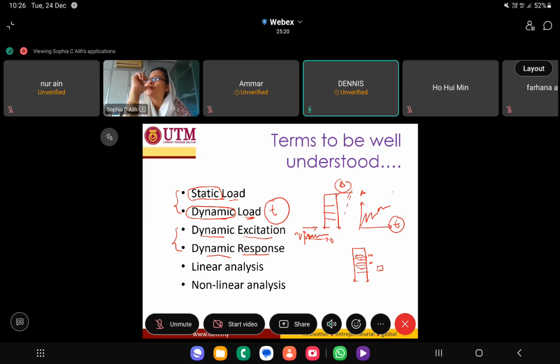force method, right? Then what you did is that you have this building, and then you calculate how much is the base shear, and from this base shear, you distribute it to this level. And this base shear you calculate based on the equation that you get from the code. Is it correct or not? Yes. So is this static design or dynamic design? Static. So just now you said dynamic. You take back your word.